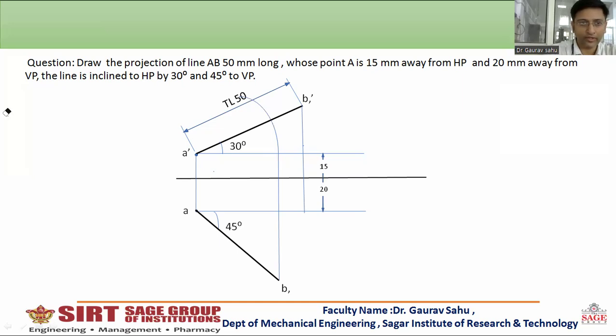I can annotate over here so that it will be remembered by you. This point is capital H and this point is capital E. Okay. So pin on A dash and pencil on H, draw the arc overhead. Step number 4: pin on A dash and pencil on H, draw the arc above, and pin on A and pencil on B, draw the arc downwards. So this is step number 4.